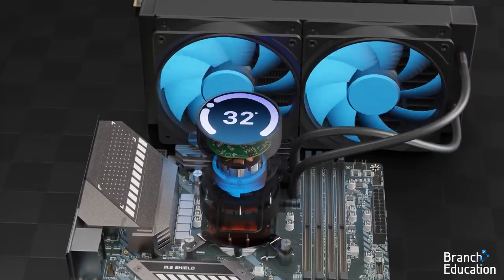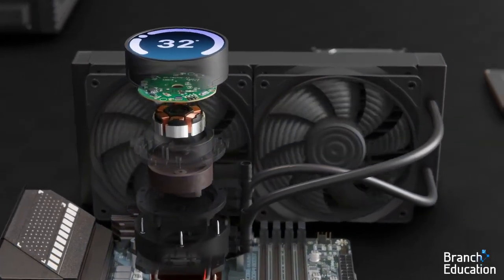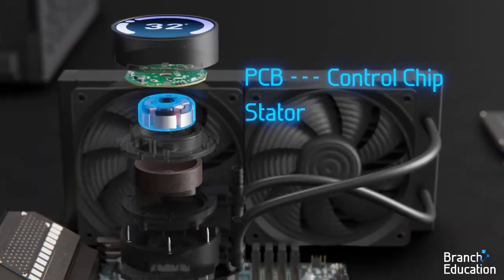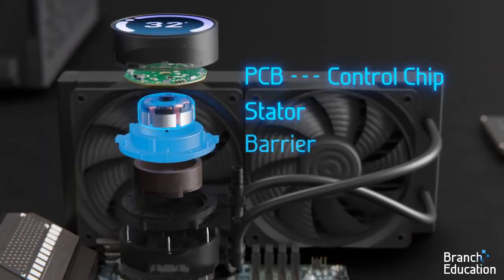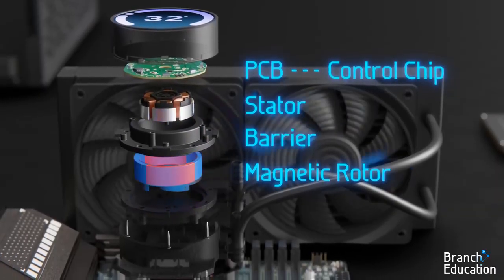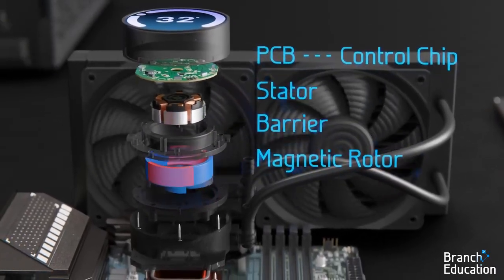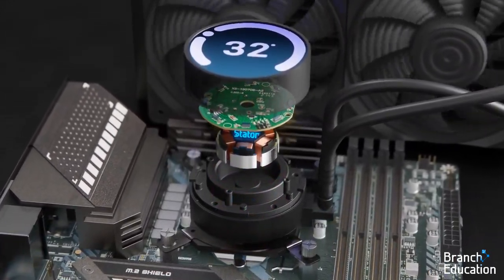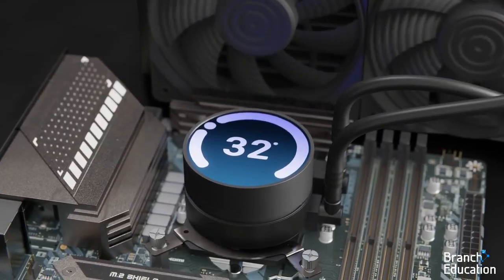The pump is a brushless DC motor constructed from a PCB, a control chip, and a stator on the dry side, a barrier in the middle, and then the permanent magnet rotor and impeller on the liquid side. There's no mechanical connection between the rotor and stator, thereby preventing any leaks of the cooling liquid.